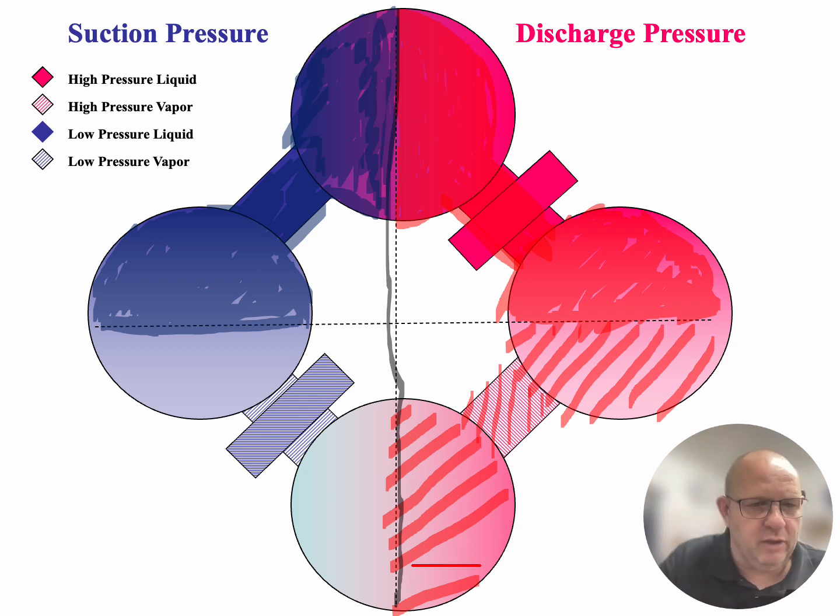Now, right in the middle of the evaporator, and this is the next device that we have sitting here, it's called an evaporator. Remember, things within our system do what they are named. The compressor compresses, the condenser condenses, the metering device meters refrigerant, or the expansion device expands it into a very large area, and then the evaporator will evaporate that refrigerant. How is it going to do that?